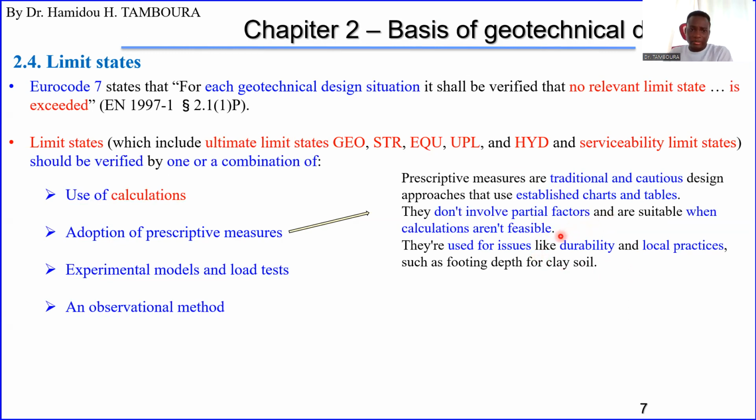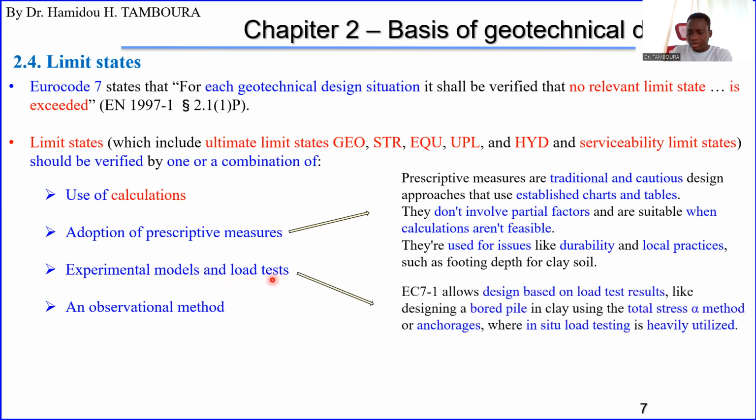Very traditional way. And then we have this experimental and loading test. Eurocode allows design based on loading test results, like designing a borehole pile in clay using total stress method, and anchorage, where in situ load test is heavily utilized. And then we have this observational method.